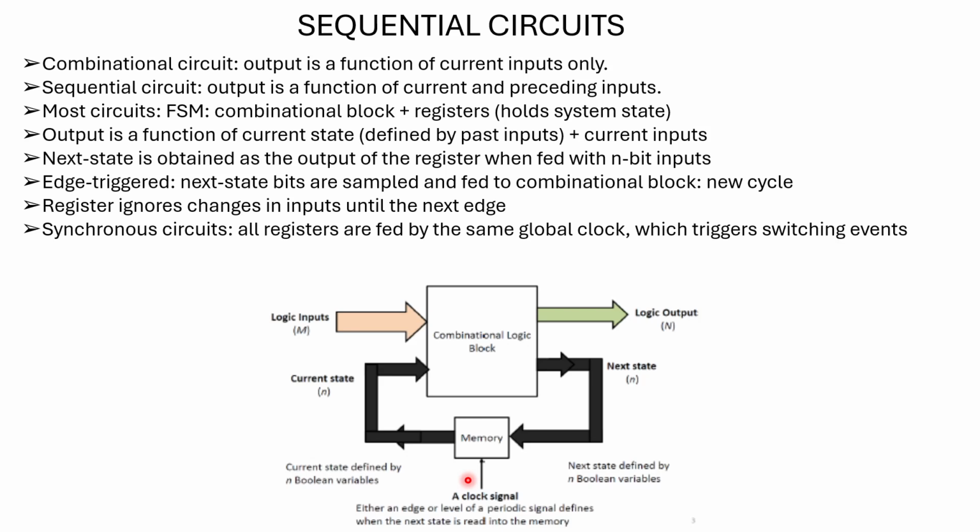So we have these synchronous circuits. What are these synchronous circuits? Synchronous circuits are circuits in which all the registers are fed by the same global clock. So everything is being maintained by one clock, which triggers switching events. And one thing about this is that the next cycle can't begin unless all computations have been performed. So the time period should be such that all computations in a sequential circuit can be performed. Unless those are complete, we can't begin the next clock.